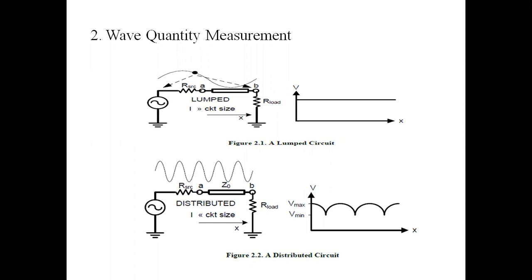Under the condition where the load impedance is equal to the characteristic impedance, the power is fully absorbed. To keep the reasoning simple, real impedances are assumed here. If the load impedance is different from the characteristic impedance, the ratio of the voltage and current will change at the point where the transmission medium changes. As a result, the load will not absorb all the power, and a portion of the power travels back towards the source. Given this characteristic, we can refer to the system as having both incident and reflected waves.